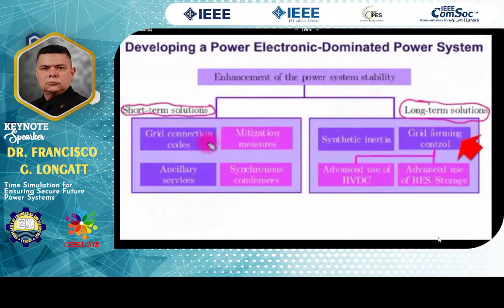And what I can tell you is that many other countries around the world have already created or opened the possibility of including more power converters in the grid code. For instance, in the UK, we are already defining the minimum characteristics of the grid forming converters inside the grid code. Okay? In other countries, we have been using what we call auxiliary services.